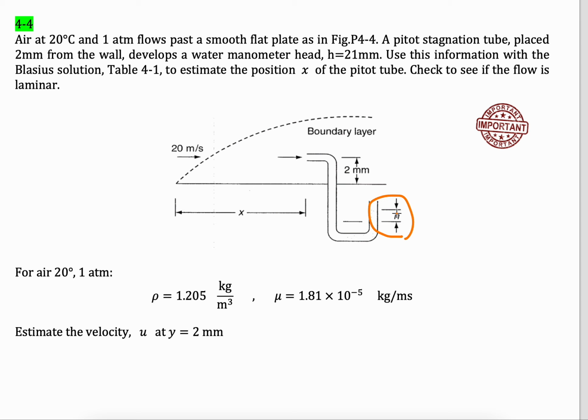So this is the idea of how we could determine the pressure profile on the flat plate. One idea is by using the pitot tube like this or the U-tube manometer. When the fluid or the air flows inside this tube, it will push the manometer fluid here. I think you already know about this.